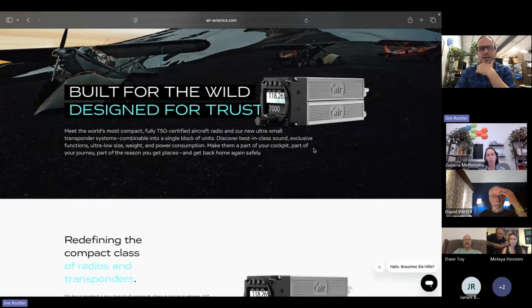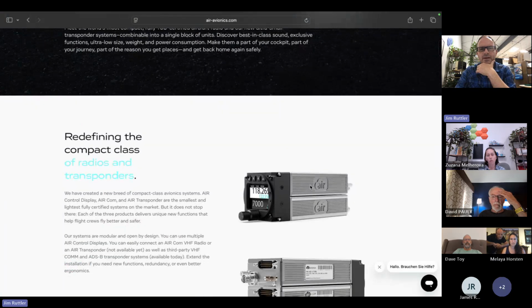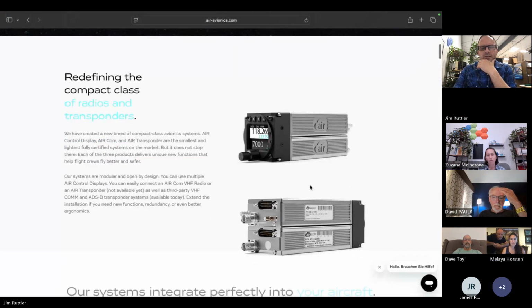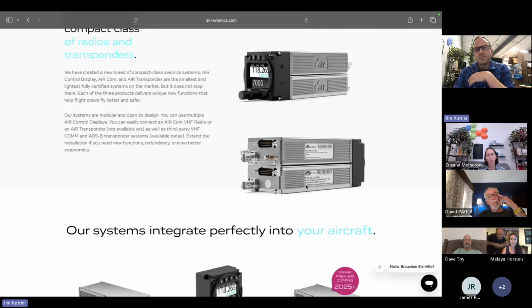They're capable of plugging directly into the back. And if you just had comm, you would just hook up. That's what I have, one of these, and then my top one is empty. But with it empty, I've got the static port exposed on the back of the ATD 57. But you can see right here, I can't highlight it, but right here is another alternative static port pass-through if you're featuring both a comm and a transponder.